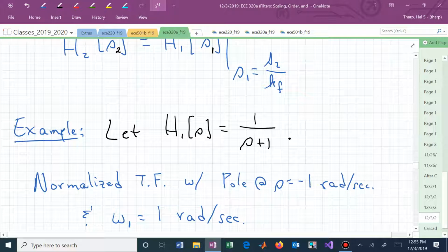So you know its DC gain, and you know where its pole is. You know now that's the break frequency, and after that the magnitude is sloping how much? How fast is the magnitude response rolling off? Minus 20 dB per decade, or minus 6 dB per octave. Again, two answers, depending on how you want to express the slope. It's the same slope or equivalent.